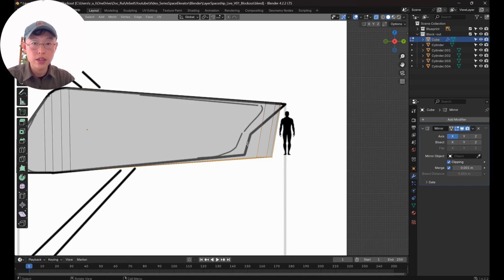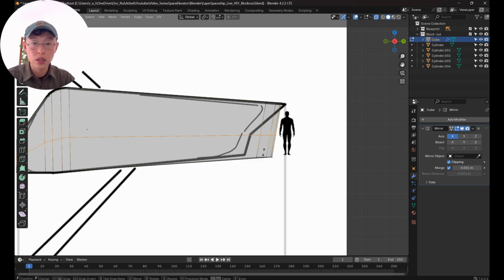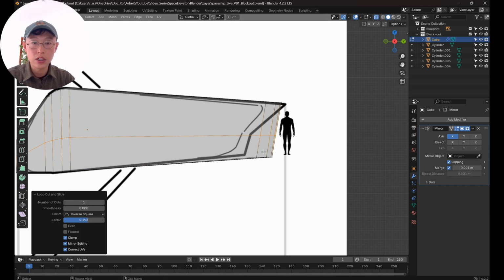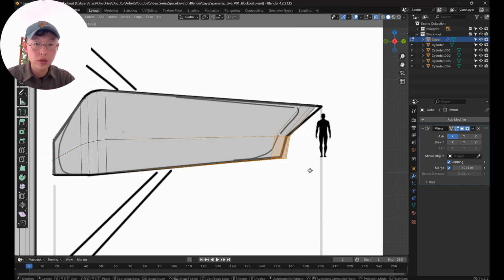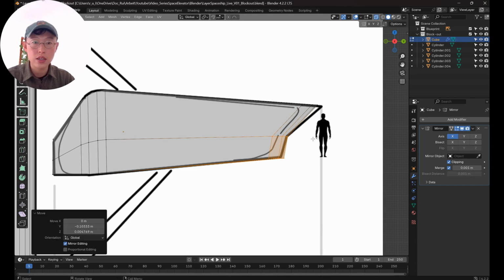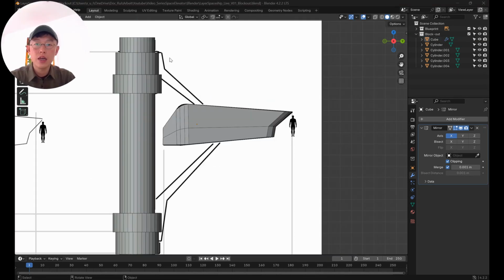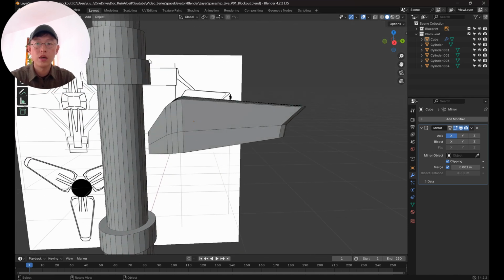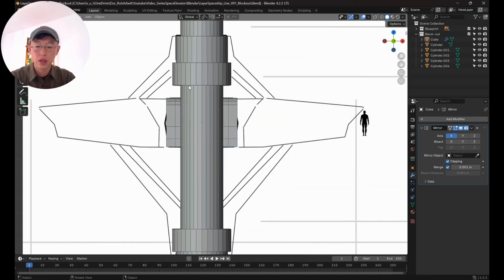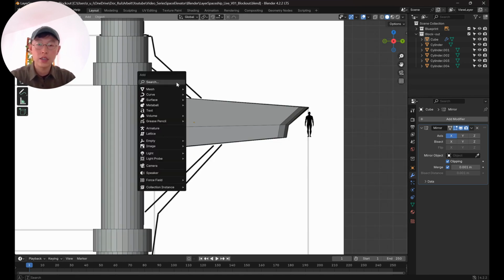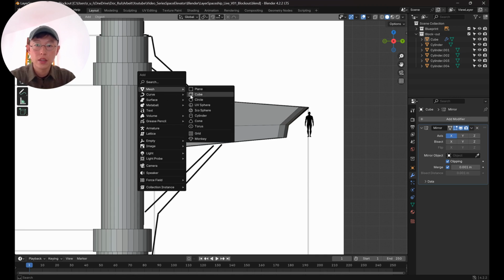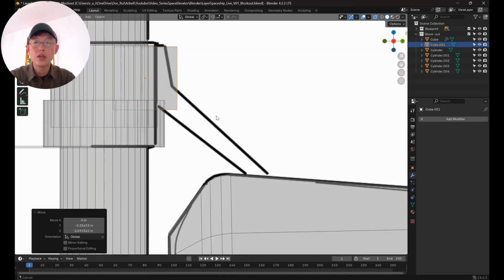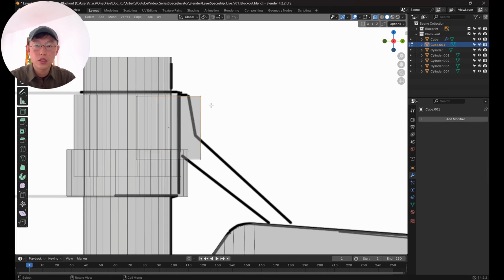And now there is this kind of angle. So let me add one more edge loop and pull the whole part to this side. It is time to add this two construction which connects the cabin with this ring. And by doing so, I'm gonna add a cube again. Hit transparent, go into edit mode. Double G to slide along edge.